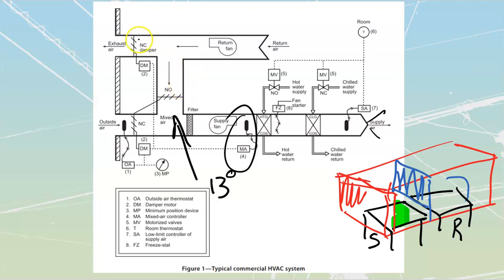I'm going to try and achieve that by, if I've got way too much heat coming in from here, based upon what my outside air temperature is here. If the outside is cold and my air coming in from the building is hot, I'll just divert some of it outside, take in some cold from the outside, etc. I do also need to have that minimum position that is going to give me that minimum healthy amount of fresh air inside of there.